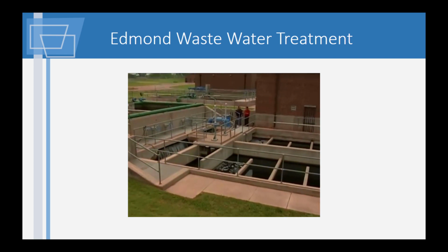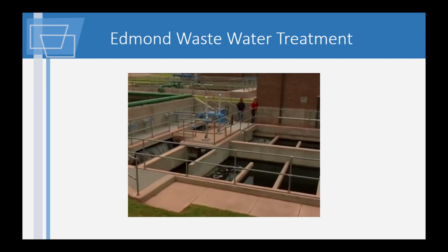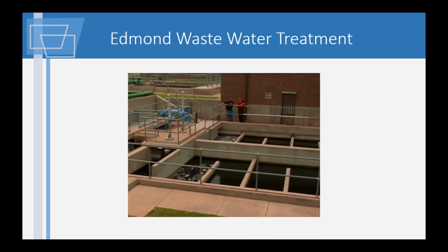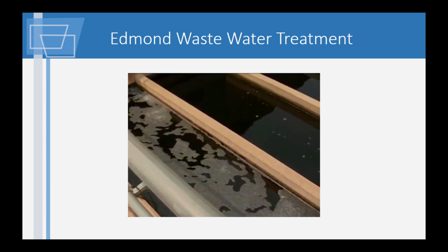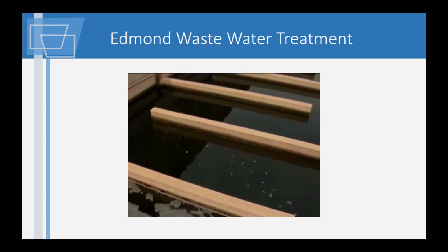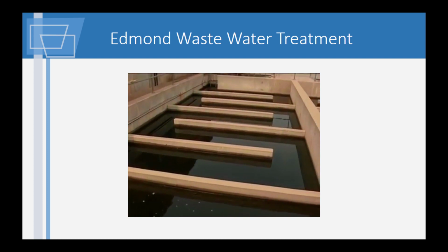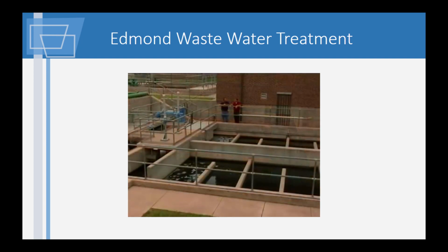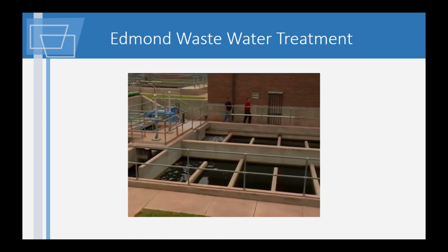Okay, so you chlorinate this water. Yep. And as I can see, it's flowing through here, and you've got a maze. What on earth does this do? The maze is to make the 30-minute contact time required to kill pathogens in the water. Instead of letting it run straight through, it has to wind through a maze to make sure it has its contact time. Slows the water down. Absolutely. By this time, the water is pretty darn clean at this point, right? Yeah.